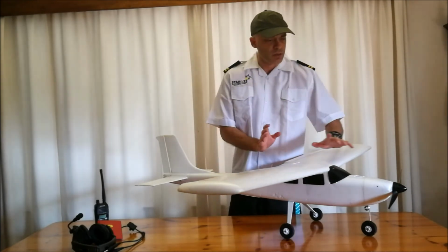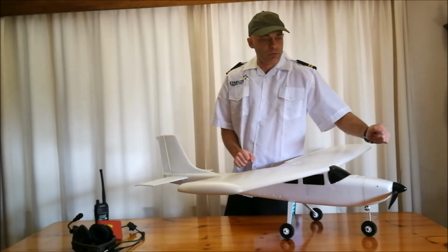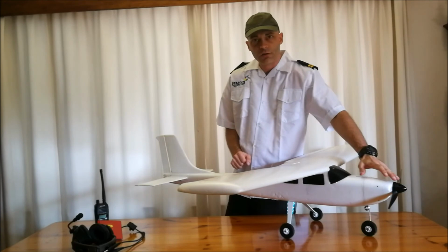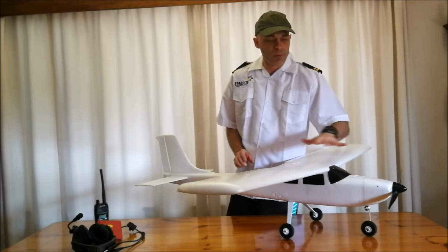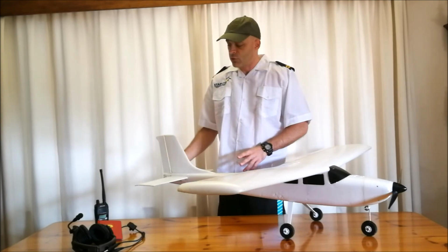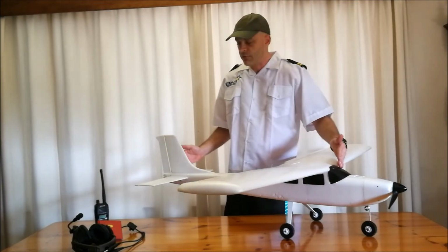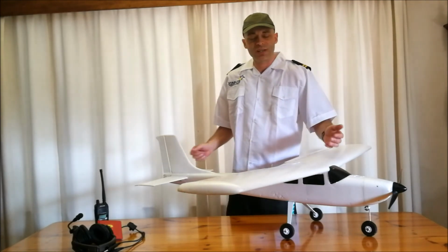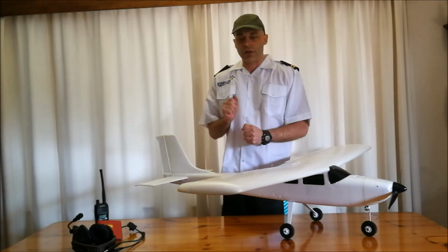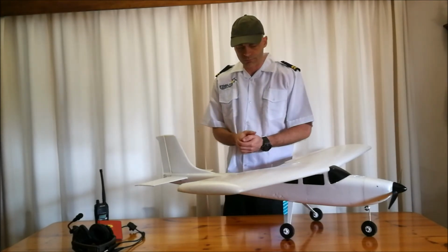Yet if you can have the weight towards the front of the aircraft, like you'll often find the engines are in the front of the aircraft, a lot of the luggage or people might be sitting towards the front of the aircraft, then that will cause it to have a longer arm length, and therefore there will be a larger moment. So there's less input that the pilot would have to give to control these surfaces.